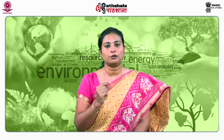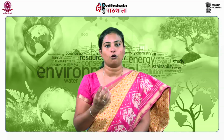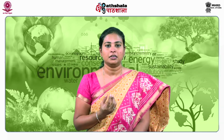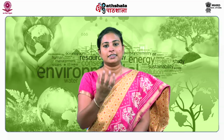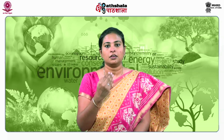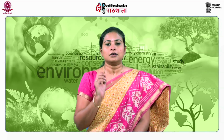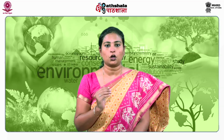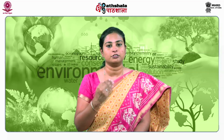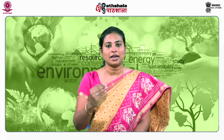Before discussing leachate management, you should know what leachate is. Leachate is nothing but a watery material that oozes out of the waste. Waste, as you all know, has some amount of moisture in it. Biodegradable waste contains some moisture, and once degradation starts by bacterial or microbial activity, it starts releasing water. This water comes out as a dark brown colored liquid called leachate. This leachate is highly toxic and requires proper management before disposal. Otherwise, it will cause a lot of environmental pollution, mainly affecting water and soil.